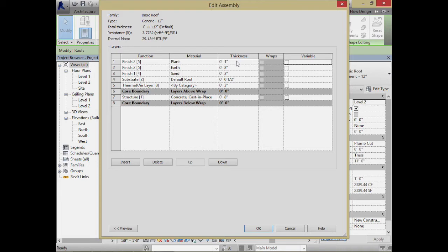You can see I've actually gotten it up to close to 2 feet. It's almost there. Notice though, interestingly, in the scheme of things, it has kind of an interesting set of properties. Green roofs are good on thermal mass. They've got a lot of mass up there. So if it's holding heat, it's going to radiate it slowly. It's like a big absorber, like a big sponge. It's kind of a buffer. So they're really good on that.